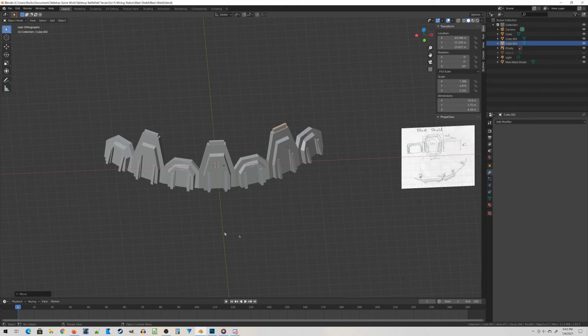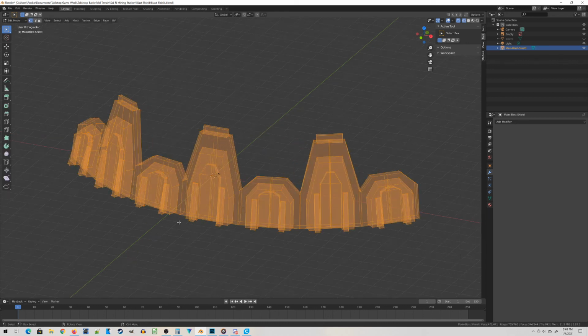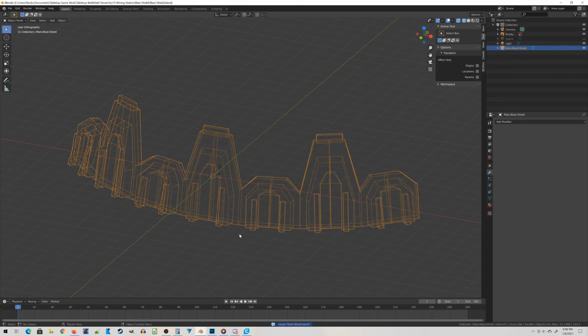Let me send this over to my slicer program and we'll 3D print it up. Oh yeah, just because you should always do it and I forgot to tell you to do it. Let's go into edit mode one more time. Have everything selected and press Shift N and then export to your slicer programs, just to fix up any weird anomalies from various Blender math operations. Well, there you go. That brings us to the end of this tutorial.